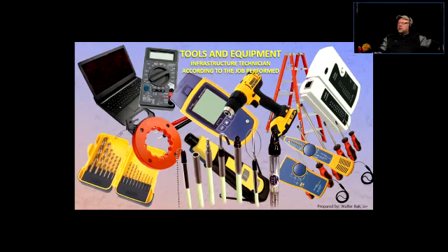Because once you look for that tone with the probe, and the probe has a little speaker here, when you move that probe close to the wire, you're going to vaguely hear that tone. If you move closer and closer in that area, you're going to hear that tone stronger. And if you touch the pair with the tip of the probe, you're going to hear a really strong signal, right?